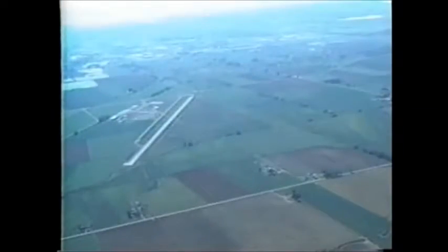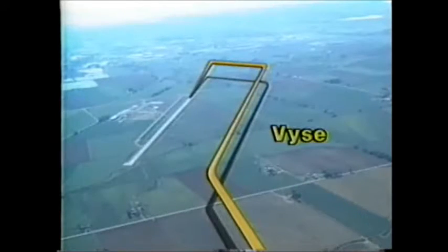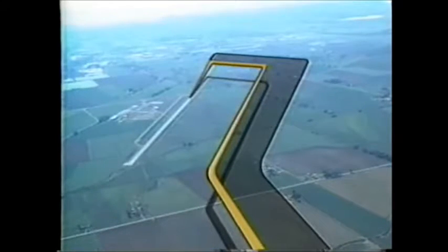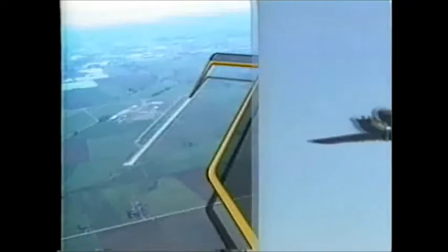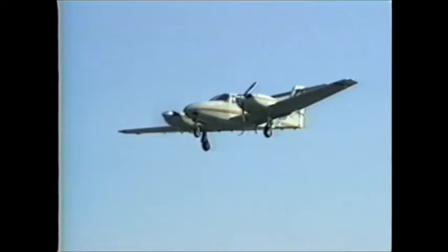Maintain the airspeed at or above VYSE throughout the pattern until the landing is assured. You may want to fly a larger pattern to allow for shallower turns and better visibility. Do not lower the landing gear until the landing is assured. Delay lowering any flaps until the gear is down and you are absolutely certain of making the runway.